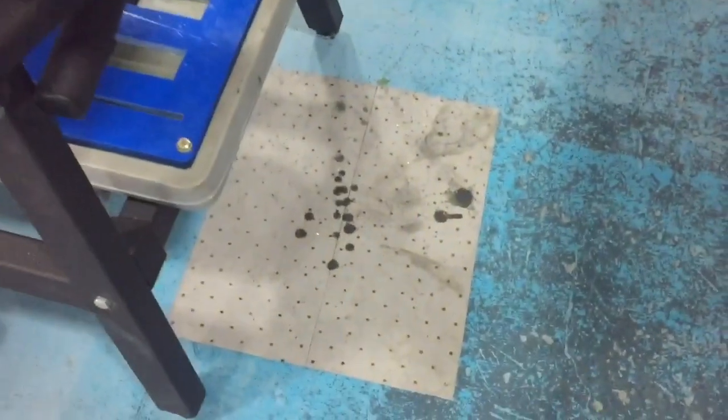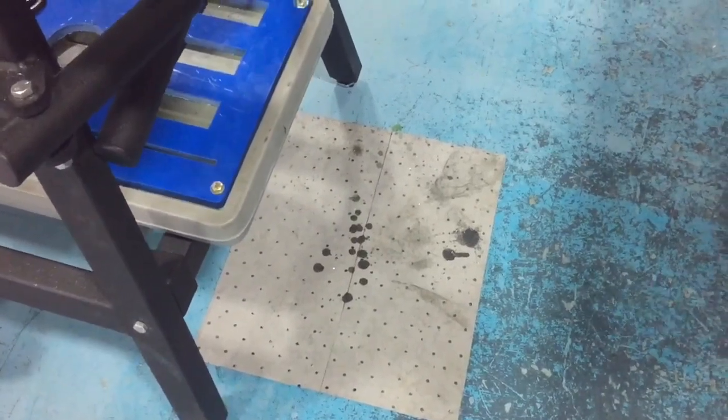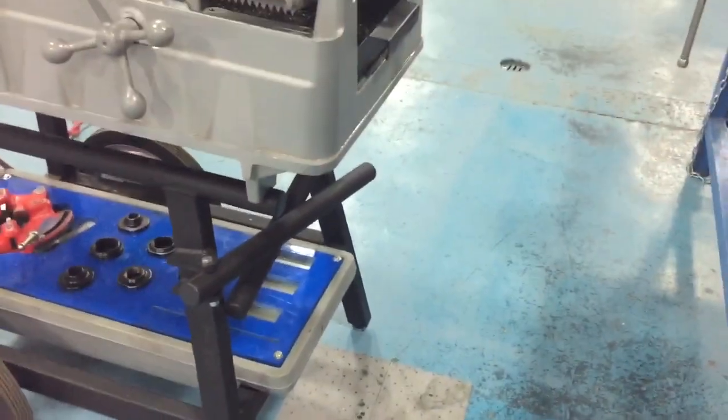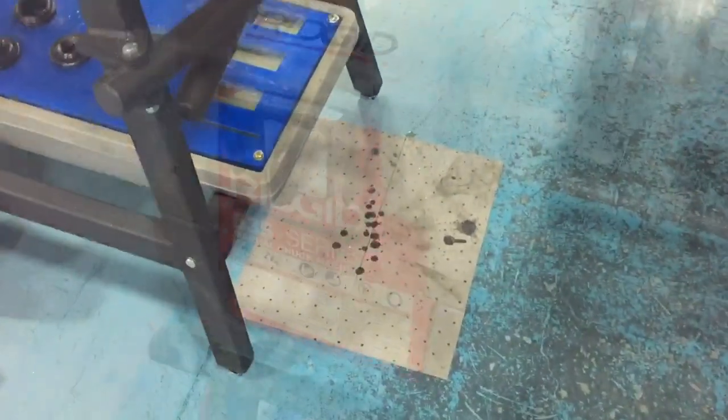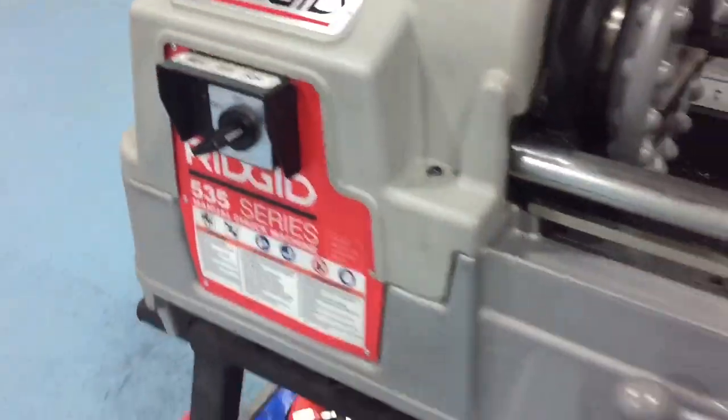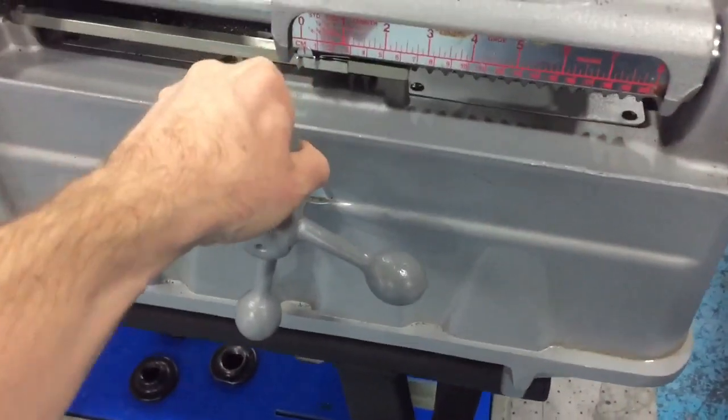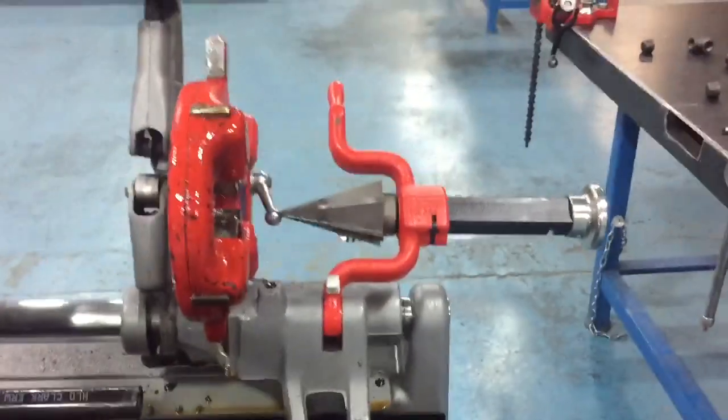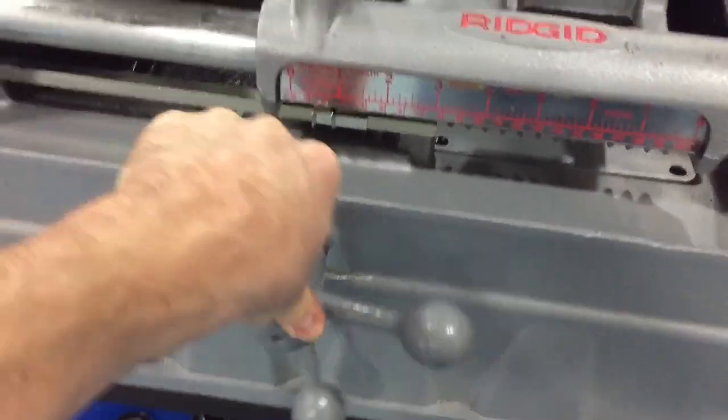All right, so you can see I've already got some oil dripping on the floor right here, so we're going to make sure we have absorbent pads down here near the front of the threader before we use it, just so we're not making as much of a mess. All right, so I'll put the switch into forward position here. Right down here we've got a wheel that we can use to move the reamer back and forth. You can see this wheel right here.